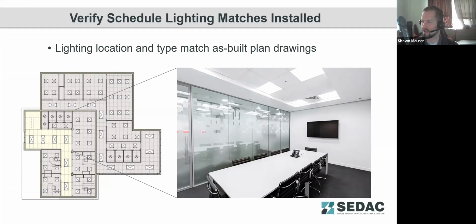A conference room may have bright white lighting for a general meeting and then dimmer, lower color temperature lighting for presentation modes to reduce glare on surfaces. And so reviewers are going to be looking at the maximum output from those devices and making sure that it complies with your watts per square foot lighting power allowance.